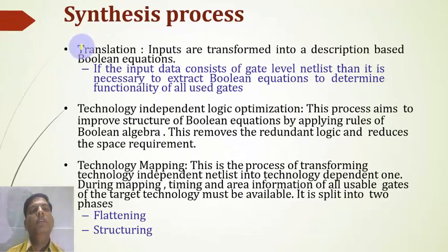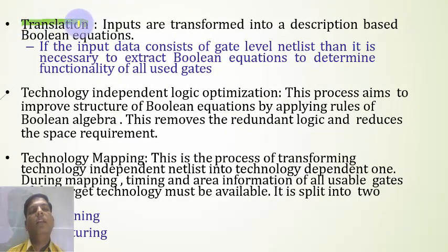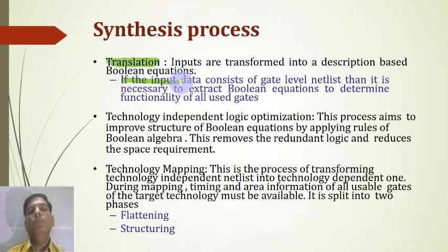So here, in brief, is the synthesis process. Translation means inputs are transformed into a description based on Boolean equations. If the input data consists of a gate level netlist, then it is necessary to extract the Boolean equations to determine the functionality of all used gates.